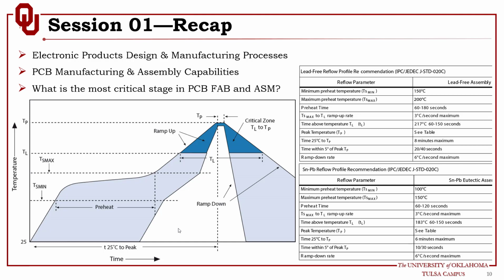And the second stage is where you have the temperature ramp up. At this point the solvent evaporation is complete and the flux starts its deoxidization action. So the ramp up is part of the reflow stage, so it's in blue here.